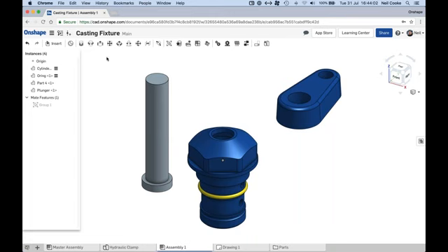Now, the way we assemble parts together in Onshape is by using this bunch of mates here. So there are 7 different mate types: fastened, revolute, slider, planar, cylindrical, pin slot, and ball. Okay, you're probably not going to use those very often. There's also some extra ones for parallel and tangent, which is more for simulating cams or making sure a robot gripper, for example, stays parallel to the floor, something like that. So you want to add those 2 constraints in those instances.